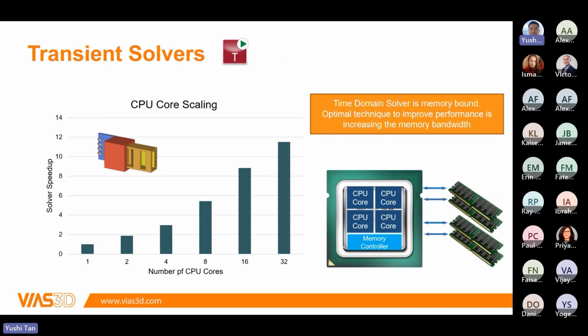Now, on the other hand, I know some of you use the time domain solver quite a bit, the finite integration technique, FIT, and also the TLM solver, transmission line matrix method. Similar logic applies here, but the time domain is mainly memory bound, meaning the memory modules compete for access through the memory controller to communicate with the CPU. So the main thing here is memory bandwidth.